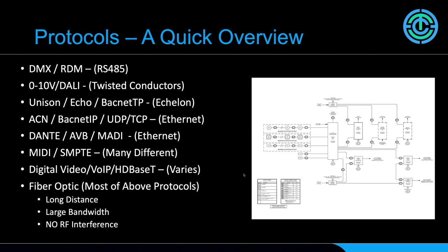And it's important when you're talking about integrated systems that if somebody says that it's a Cat5 system, that you clarify whether it's an actual Ethernet system that they're talking about, which is the protocol that our computers use to communicate TCP data and IP data, or whether it's just a Cat5 native system where the manufacturer has built their own standard of communication protocol that they're using just on simple Cat5 network cable.